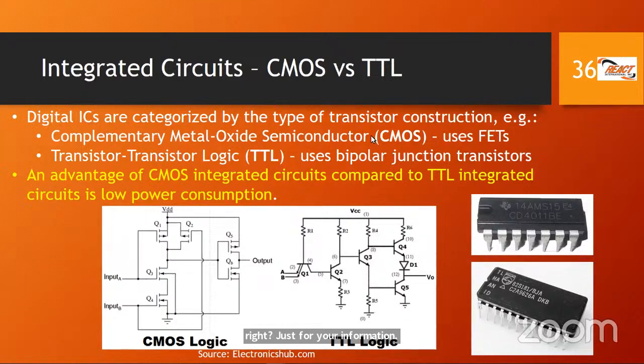You don't want to zap it, especially in some countries where the humidity is such that, sometimes you're walking and you go and you touch a vehicle and bam, you get a zap, or a door, you get a little zap, or you walk with a certain type of material clothing and all of a sudden now your hair is standing up on end, or you just touch something and you get a zap, right? So static electricity. CMOS type components are very sensitive to that. This is just for your safety and to save you. You don't want to zap your CMOS based chip just because you weren't aware of the sensitivity to static electricity.